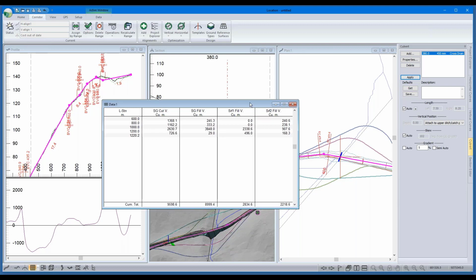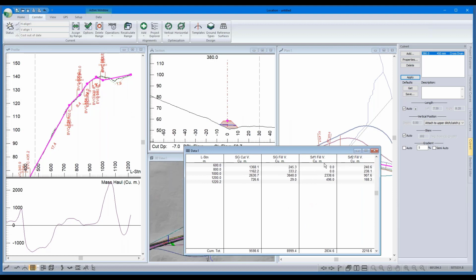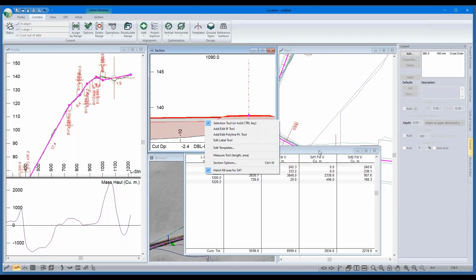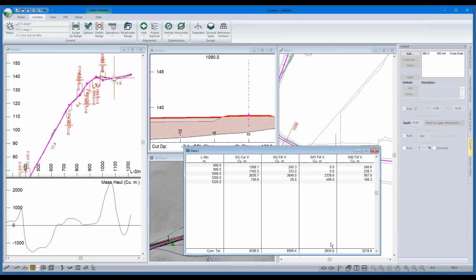My gravel surface here, I've got my material for surfacing. So surface layer 1, if we go up here, this is surface layer 1, so I'm using about 3,000 cubes of that aggregate spec, and then for the normal capping material for the road, I'm at 2,000 cubes.